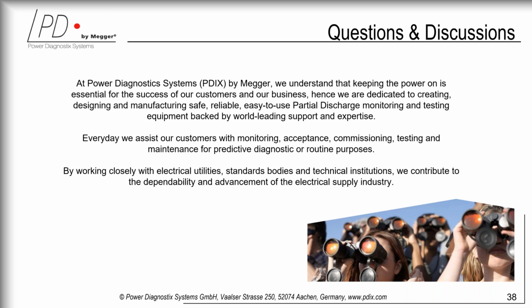Okay, so this is a very interesting question. The reliable diagnostic is obtained very quickly. Even in factory acceptance tests or otherwise, after setup, which can take hours, a test for about 2-3 hours will clearly give us a diagnostic. Do we have PD, to what degree and where, and so on and so forth. That can be done both online and offline. The question is, how long should we monitor?